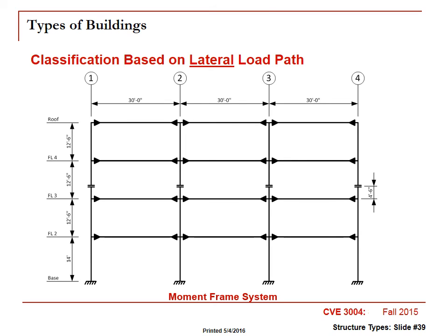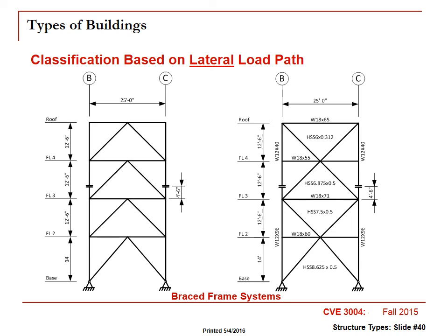Okay, and this is just again an elevation view of moment frames and so on and so forth. The little triangles are just the designators that they use to say, hey, there's a moment connection at this point. And here's the elevation showing some brace frames. Over there on the right, you can see some X bracing. Over there on the left, that's what we call chevron bracing.